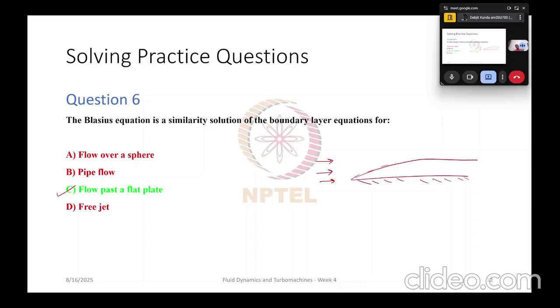This is through the act of viscosity. So instead of a continuous uniform velocity profile which was coming in, we get sort of an increasing velocity profile, or velocity gradients get set up within the boundary layer,